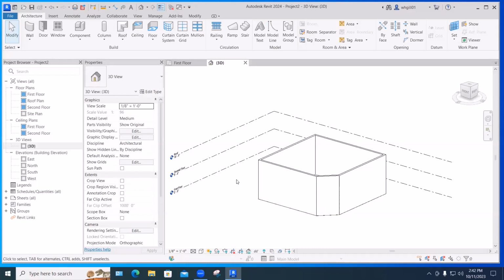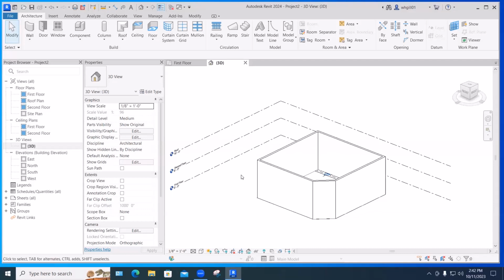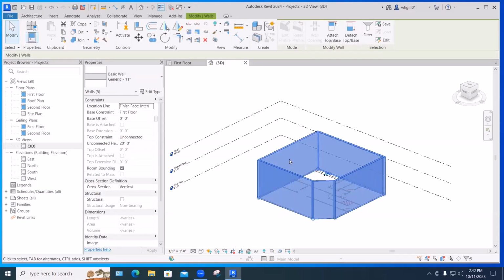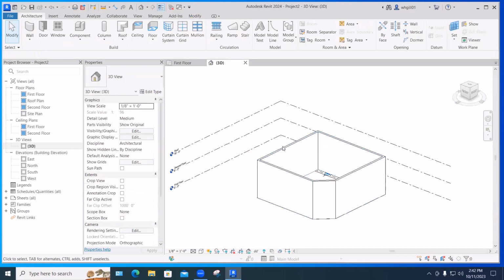It's easy enough with Revit to make these global changes, so that instead of having to pick and change and pick and change and pick and change, you can affect a bunch of things at one time. And one thing Revit can do to select multiple things that are the same type and connected end to end is to hover over one of them, hit Tab, and then click, and that will select them all. So hover till it shows up, hit the Tab key, just a tap on Tab, and then click.